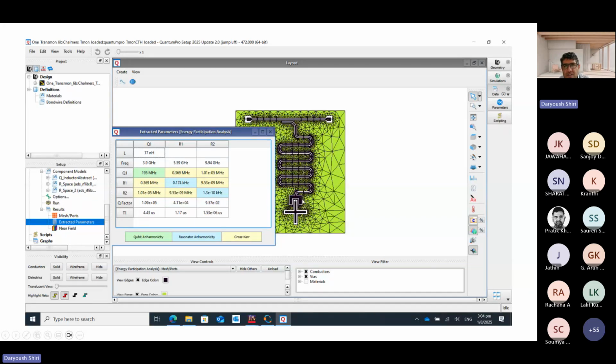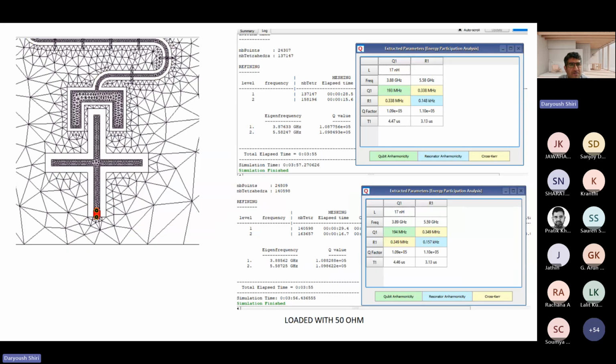So just sweep different things which are important, have plots and fit equations, and from your own fit equations, you know that if you make this claw narrower or bigger, how much would be the coupling capacitance. Is it 5 femtofarad or like 10 femtofarad, etc. So that when you look at a layout by naked eye, you can have an idea how much is this capacitance here, how much is the capacitance of this transmon, etc. So that you don't need to over-simulate things, because time really matters.